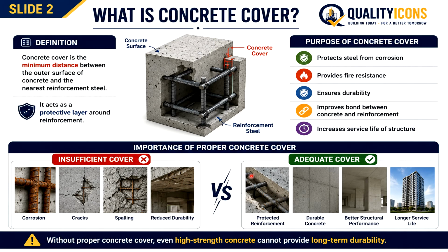This shows the importance of proper concrete cover. This entire problem happened simply because proper concrete cover was not maintained. Understood? Without proper concrete cover, even high strength concrete cannot provide long term durability.